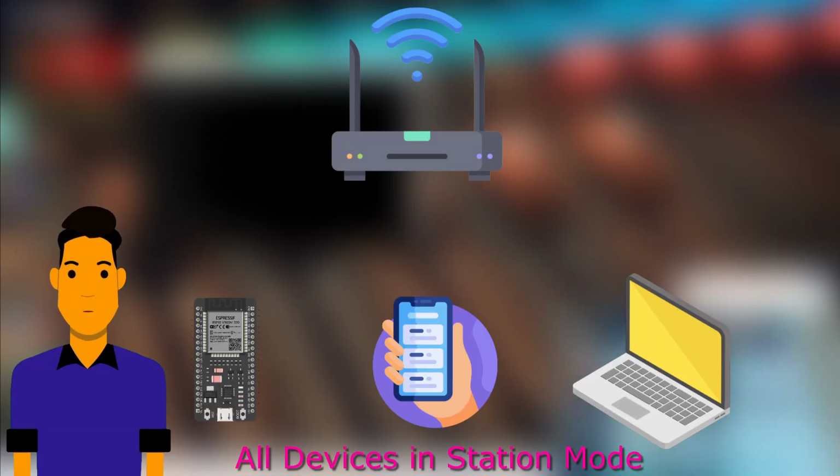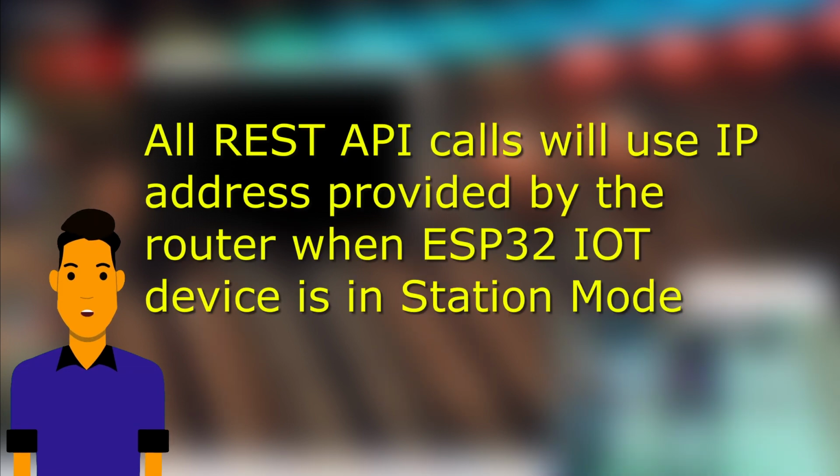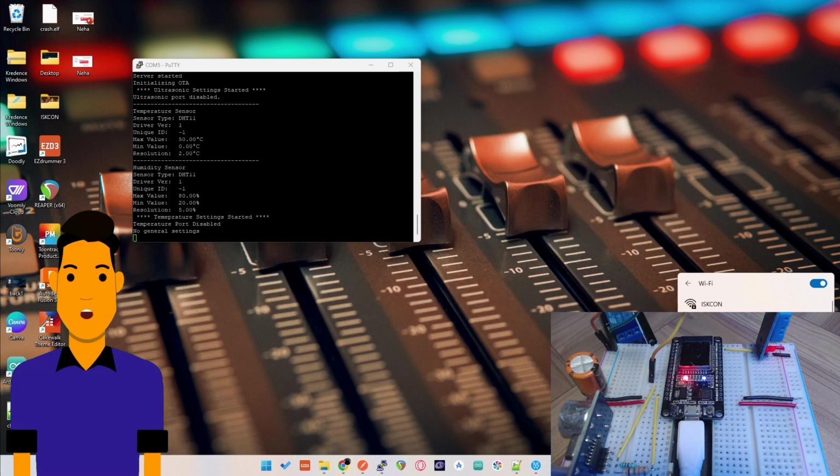The second mode in which ESP32 can work is station mode. In station mode, the device connects to your provided Wi-Fi network, and then you can actually access all the features of the device, and then you can actually sense and control the actuators that are connected to the device. So during the configuration mode, it behaves as an access point, and now what we will do is we will connect to this particular access point. And now once this happens, you can see that the blue LED on the ESP32 board will start flashing with a higher frequency.